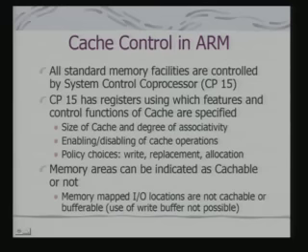Say for example, you have got an interrupt from a processor, and you would like to write back to the processor acknowledging that you are servicing that interrupt, okay, from that IO device. Now, if that write is written onto the buffer, then what will happen? There will be a time expiry before that is written onto the device. So, in between the device can again raise an interrupt which is not called for.